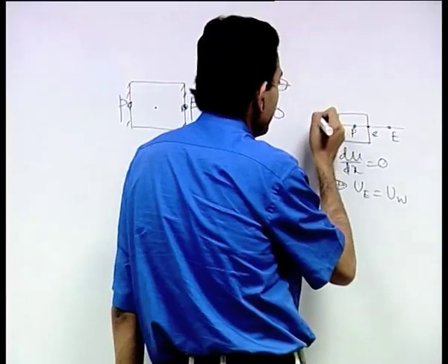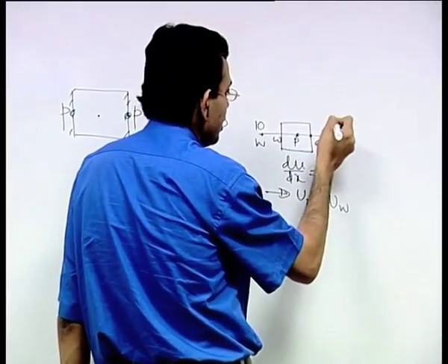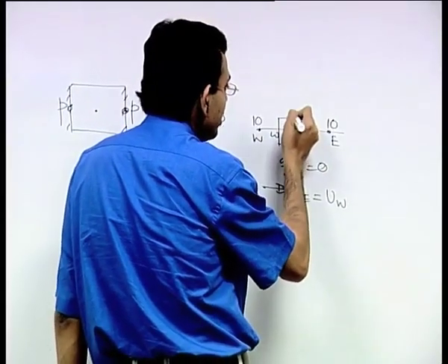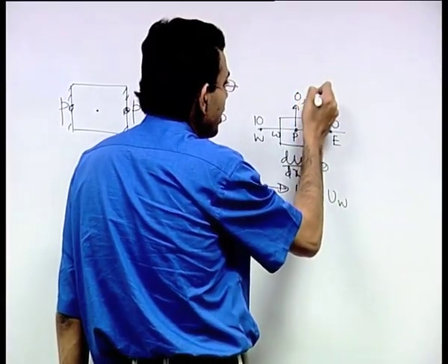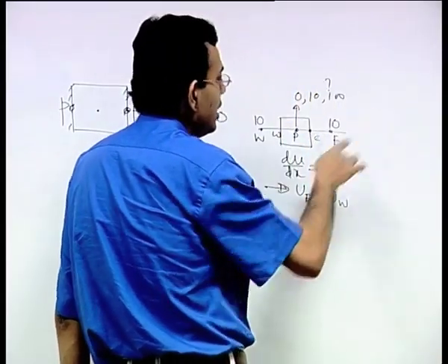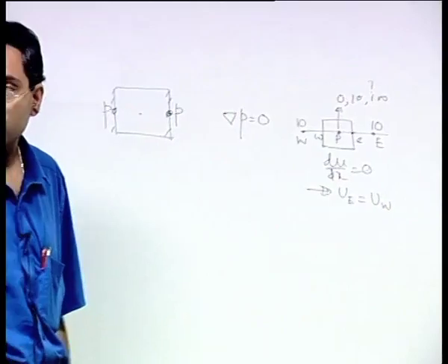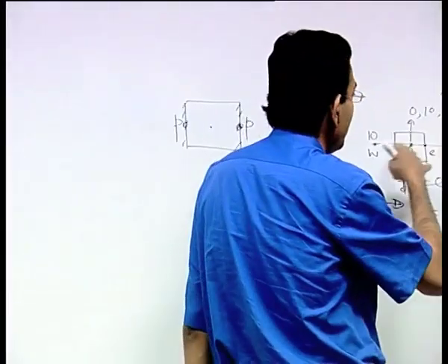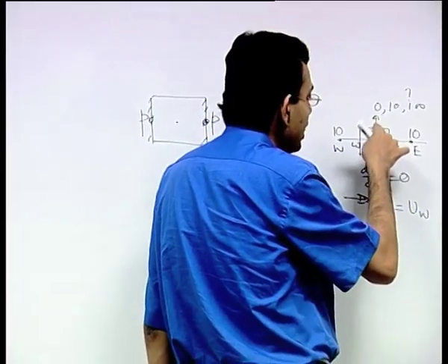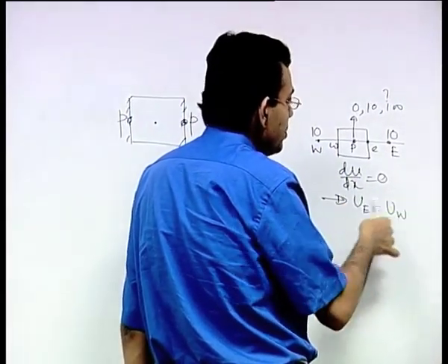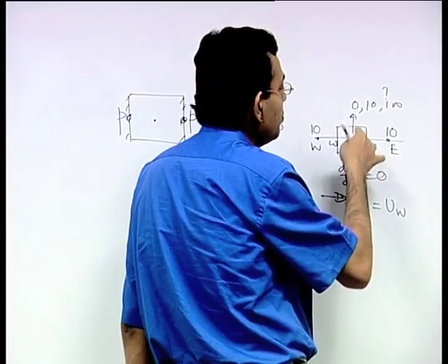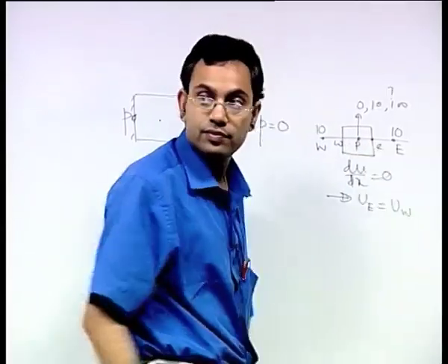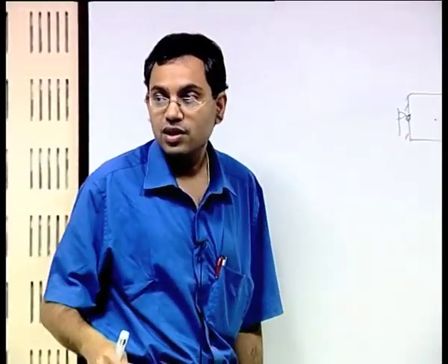So if you have a velocity here as 10 and velocity here as 10 and velocity here as 0, 10, 100 whatever, all will be interpreted as same. This is what we mean by the checkerboard type of field or a wavy type of field. So irrespective of the value here, the continuity equation here may be satisfied ambiguously with many possible values of uP. So that is one of the artifacts.